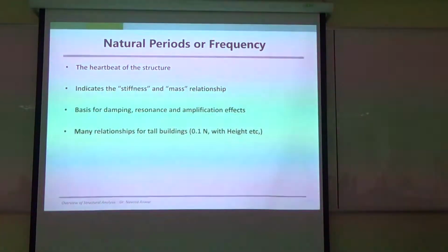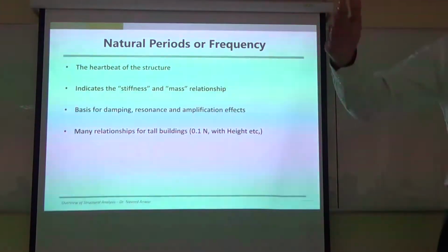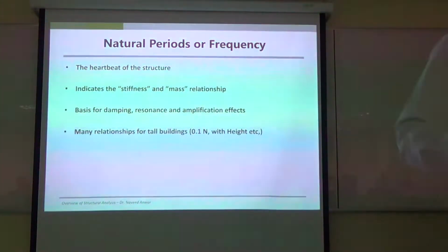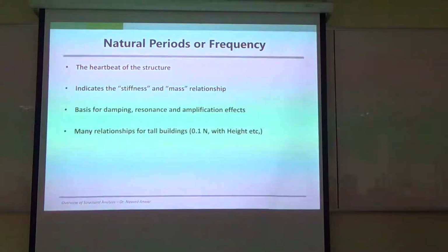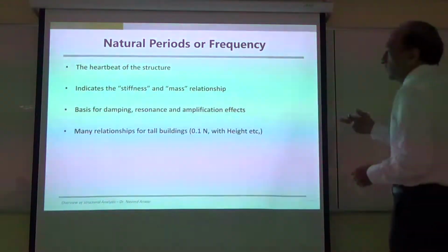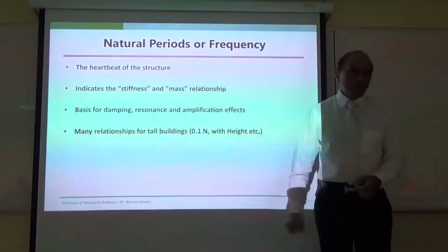You know, when you have these generators on the foundations, it's very important that the foundation doesn't start to walk. It's called walking. Sometimes if the foundation is not designed properly, when the generator rotates, it can make the foundation walk. So the foundation can move over a period of time because the movement is such resonance that it can displace the foundation. So the design of the foundation, many things depend on this one.